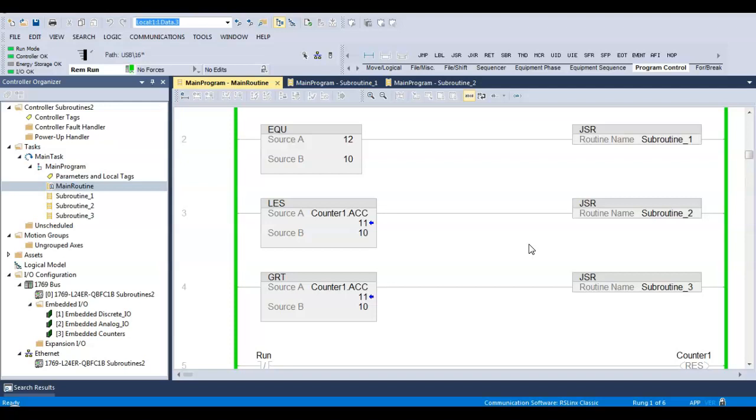Well, I'm using switches. So that's what I put my switches in there for. So what you would do is you would say, okay, what am I going to do when I run subroutine 1? Am I going to turn on outputs? Do I need the outputs on, or do I need the outputs off when I leave, right? You understand? Or make a decision. I think you just creatively come up with it. Yeah, well, that's something you're going to have to figure out because your outputs are going to maintain their state